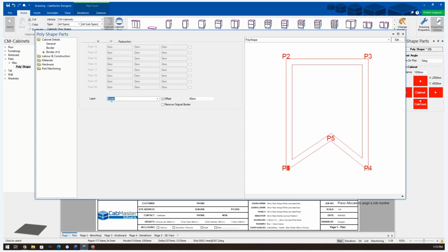And then I can change this from layer border to, say, cutout by just writing it in, or for that matter, any strategy that I might have in EasyNest. This will allow me to shaker out that middle bit or cut it out, or other ones that I want to do. So I might put in a V curve or whatever I want in there. Then I can remove the original border if I wanted, put it back. So if I had the border there, I can remove it.